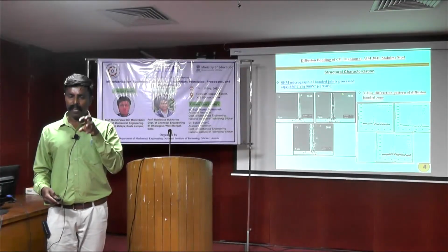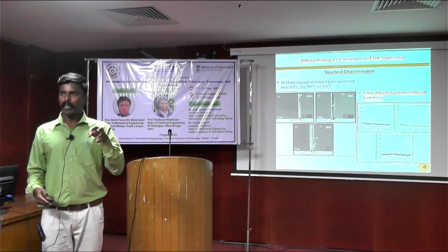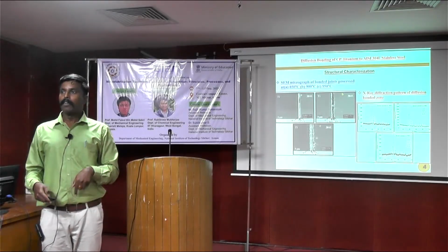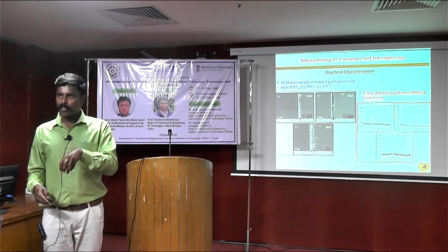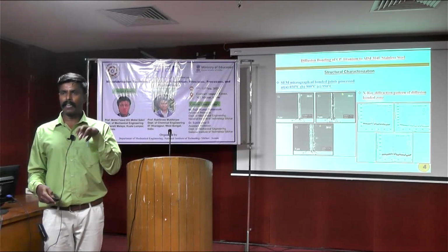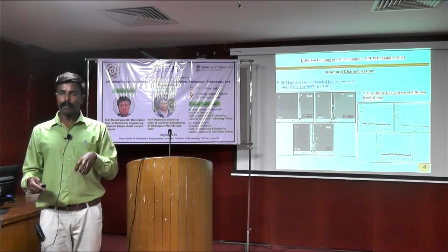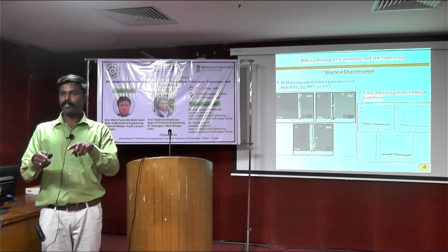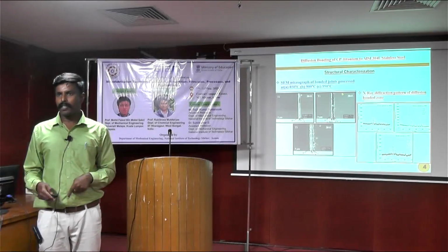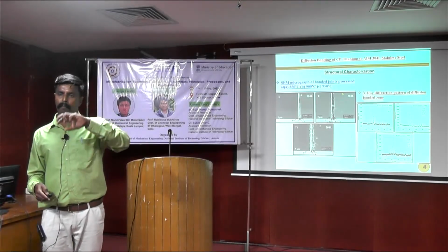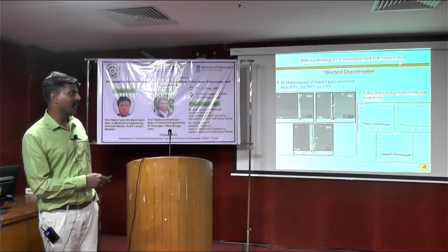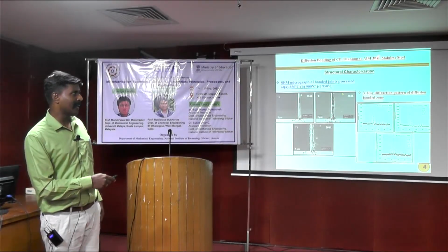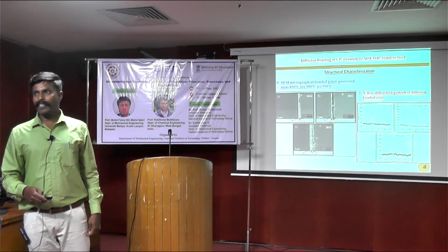The fuel is cut into small pieces and put into the dissolver tank. That tank is made of titanium because the solution is concentrated nitric acid, which is a highly corrosive fluid. To store that nitric acid, the tank is made of titanium, because titanium has high corrosion resistance. The balance components are made of stainless steel. We know 304L is an austenitic stainless steel, where L indicates low carbon to avoid the sensitization behavior.